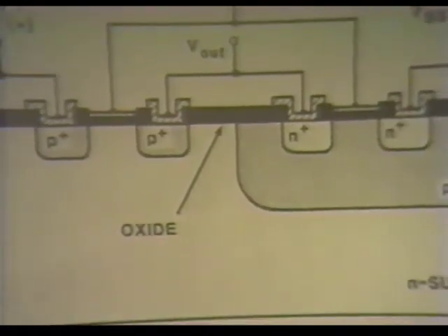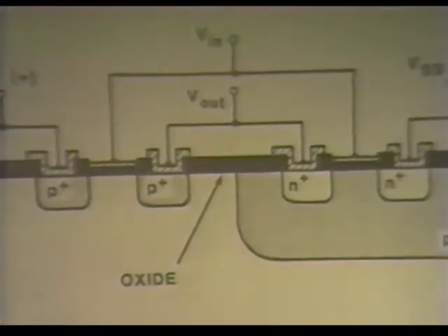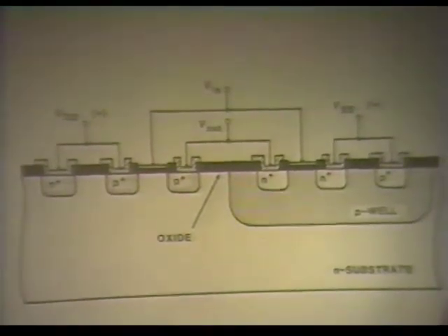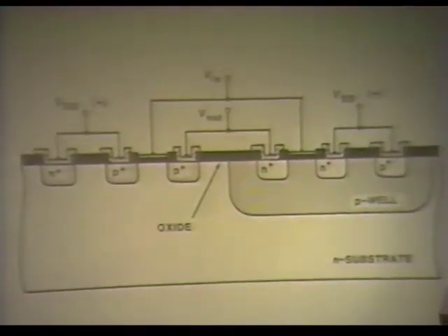And if you go draw those out, and that's an exercise for the student, and hook them together, they look just like the equivalent circuit to an SCR. And guess what? The radiation, when it generates that pulse of photocurrent, turns that sucker on. And it stays on until you turn the power off, or until you burn up the device.